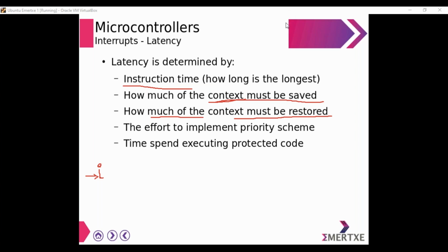And how it affects the data in the register, can you explain? You will see going ahead. Being in the ISR, there are chances that it might affect the data of some registers, not just your port B or TRIS registers. You will see ahead there is something called a shift register, buffer register, which you come across later. Those registers can get affected due to the instructions executed in the ISR. That is why we generally back it up before the ISR is handled.